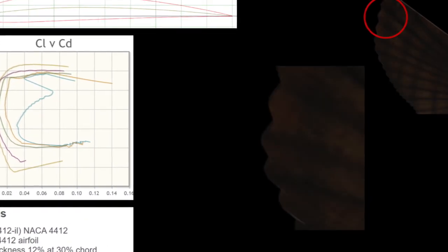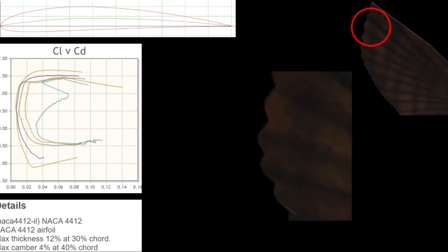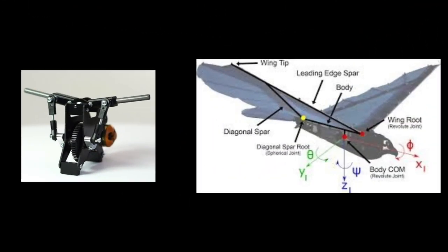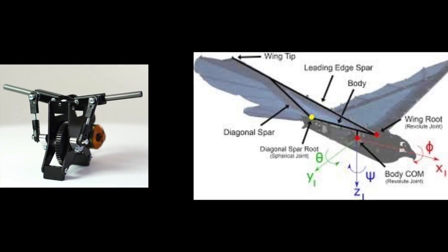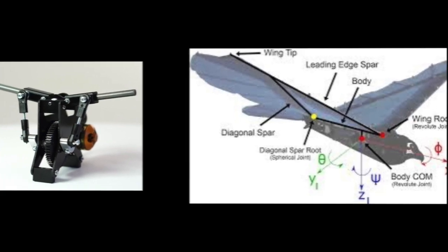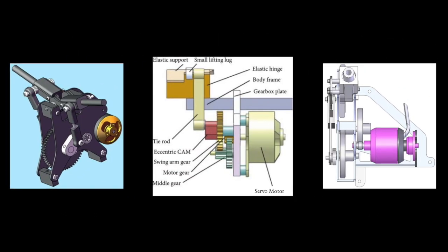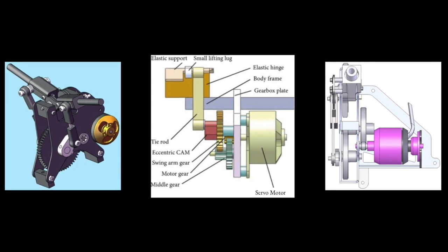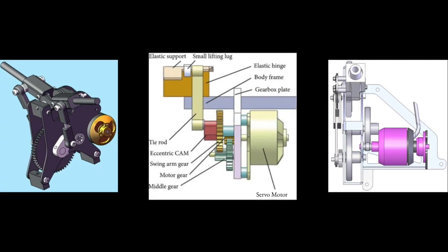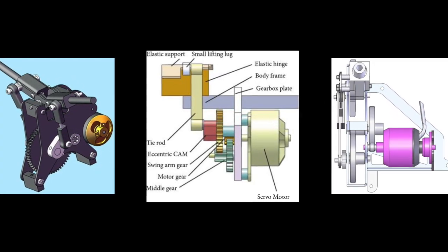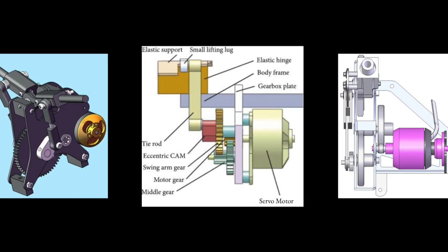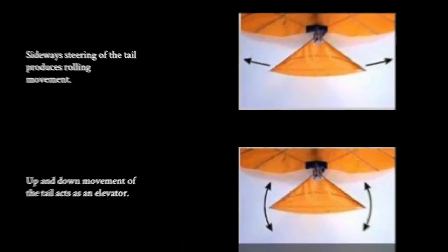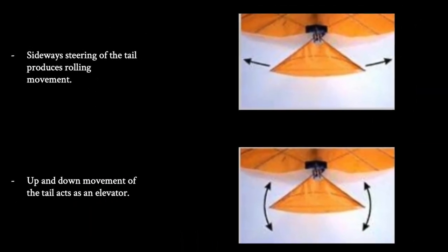Thereafter, we have chosen NACA 4412 as an airfoil and we have trimmed the wings for noise reduction. The flapping mechanism will consist of conventional 4-bar drive linkage with spars made up of carbon fiber due to its high tensile strength and lightweight. The conventional gearbox used for a T-shaped tail in an ornithopter will be used in Garud. There will be 2 motors, a brushless motor of 1200 kV for the flapping mechanism and a servo motor for the tail. An ornithopter tail solves the following purpose.